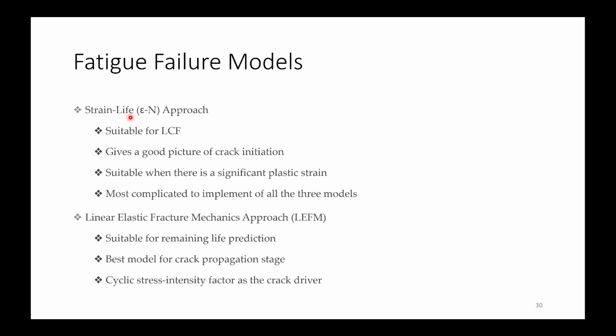Second approach is the strain life approach. On the y-axis, you'll be plotting strain. It is suitable for low cycle fatigue. It gives a good picture of crack initiation, and it is suitable when there is significant plastic strain present.